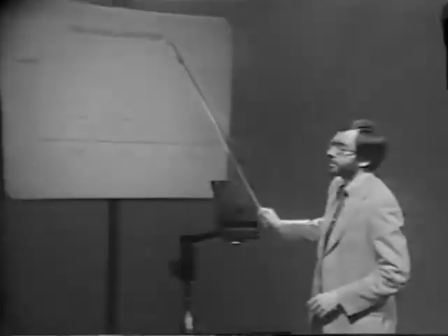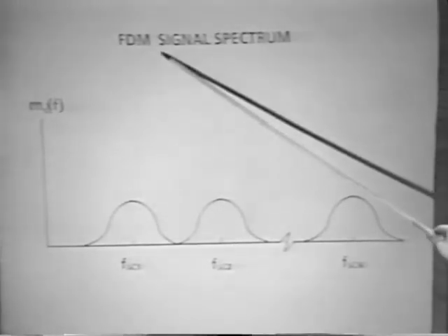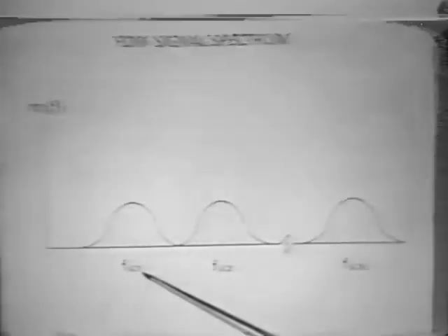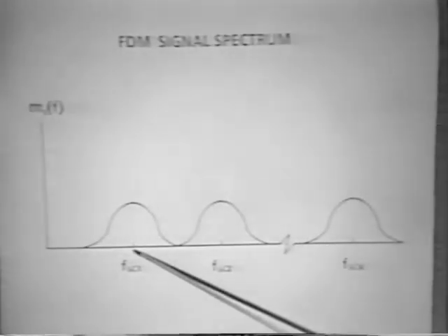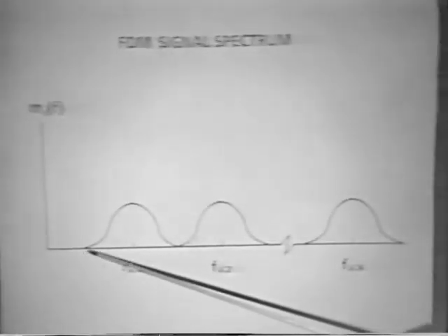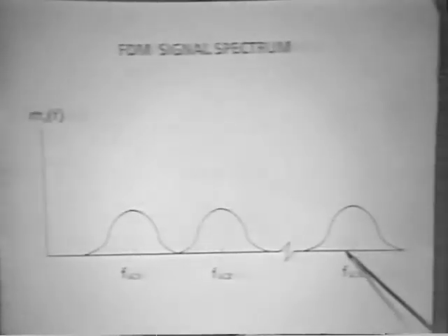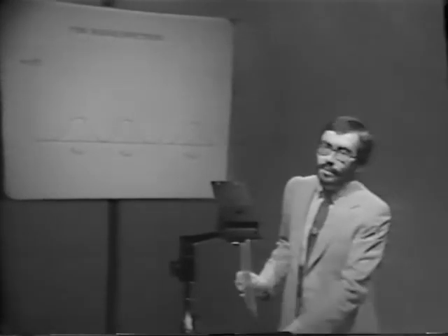That is shown here, where we show the signal for a frequency division multiplexed line. We're talking now about the composite signal that was on the previous page, and what you see is that there are bandwidths centered at these various carrier frequencies or subcarrier frequencies. And hopefully we've designed it so that the spectra do not overlap. And consequently, we have preserved the integrity of each of these signals as they are transmitted, and they're all transmitted simultaneously. Each of those frequency bands then is known as a data channel, or simply channel. Okay, that's transmission and what the signal looks like on the line.